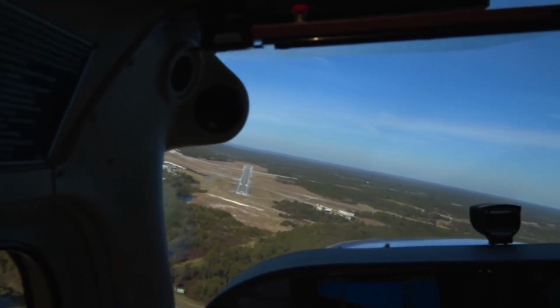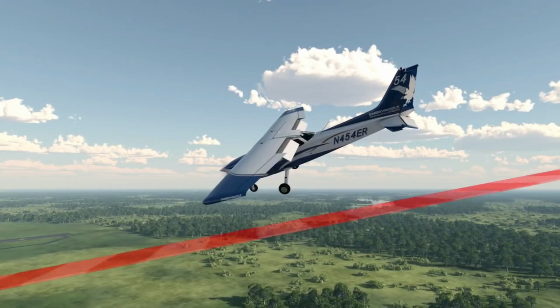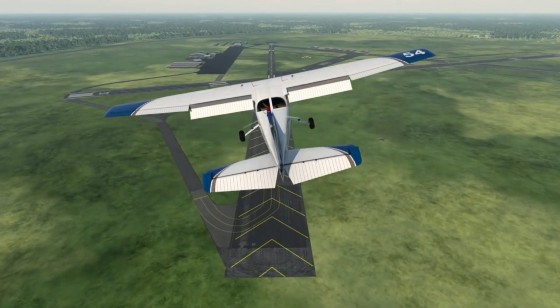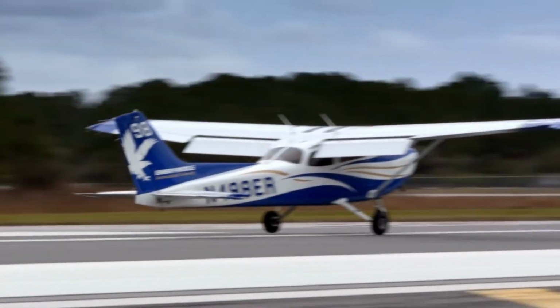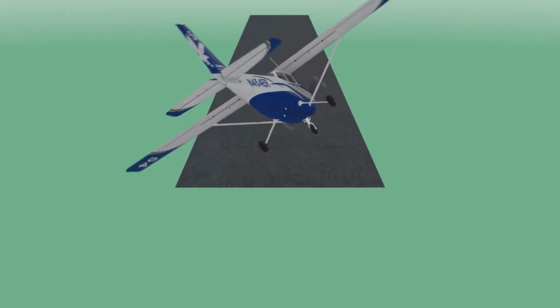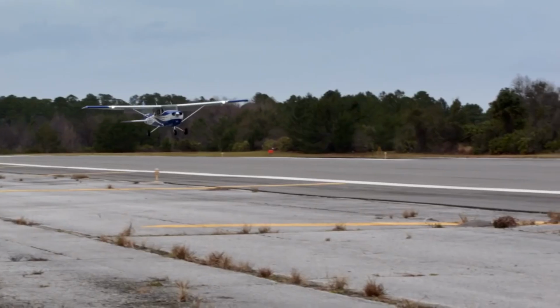Although the crab method may be easier for the pilot to maintain during final approach, it requires judgment and precise timing when removing the crab immediately prior to touchdown. The wing-low method is recommended in most cases, although a combination of both methods may be used. While current testing standards allow for either method, pilots should learn to do both.